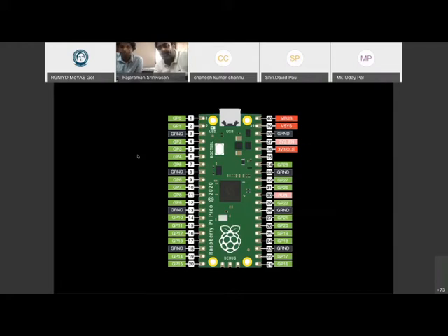Above this we have another, VBUS. The VBUS is 5 volts and it's directly powered from the USB. The power that comes into the USB is directly coming onto the VBUS. And then we have an ADC_VREF. The ADC_VREF provides voltage and a current with which you can calibrate some of your instruments.